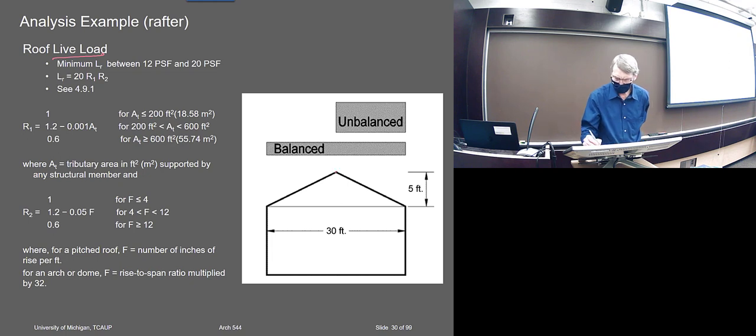We're looking at rafters, so the rafters are only going to have a tributary area on either side of the rafter, right? So if they were, we don't know what the spacing is, but say they were a foot on space, this is only like 20, maybe it's 15, this is maybe 16 feet times a foot, 16, so it's way less than this. It definitely doesn't have much area.